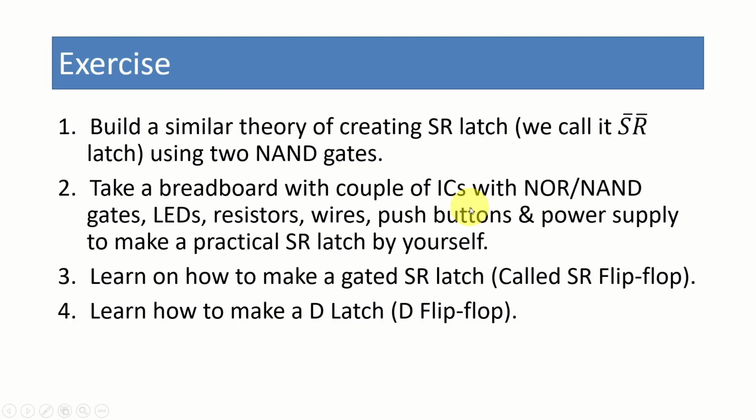So the second task that you can do, if you are familiar with the breadboard and a bit of digital electronic circuit components like ICs, resistors, push buttons, etc., is to build a simple circuit of the SR latch we discussed and see whether it is really going to remember those values. So give it a try. The third one is to learn how to make this SR latch into a gated SR latch, or what we call an SR flip-flop.